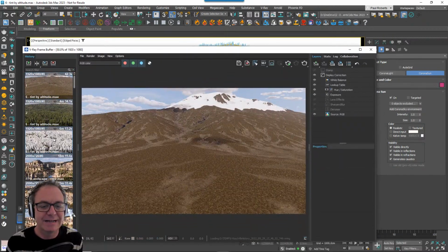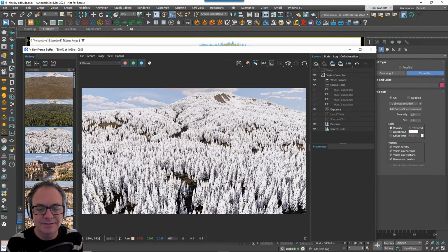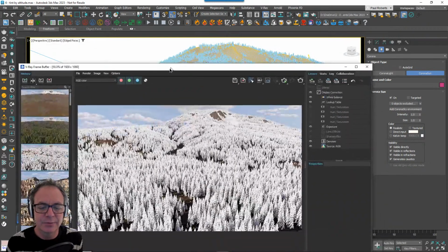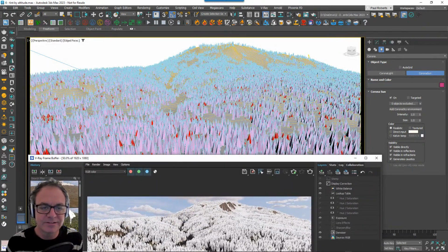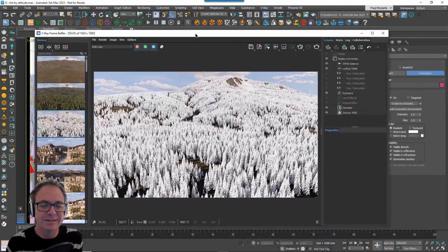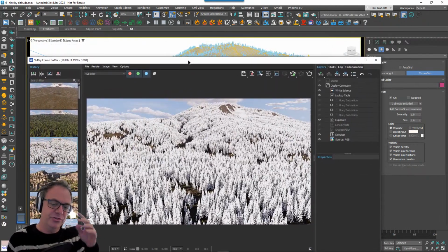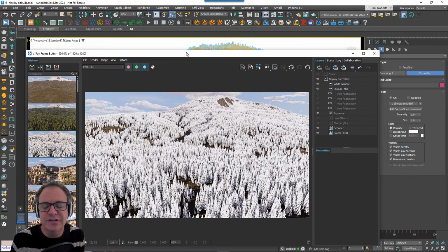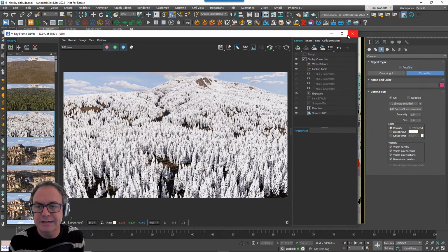And if you were to scatter that as it is, then you're going to get that, which of course has snowy trees, but only the snow line should have those trees on it, which is up here somewhere. Now I could split this into two generators, two different forest packs, one with the snowy trees and one without. But just to illustrate in this case, I'm going to remove the snow procedurally using a forest effect. You could use it for tons of other things, but this is just a really clear demo of how you can use this and how it works.